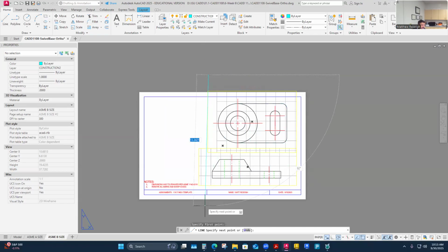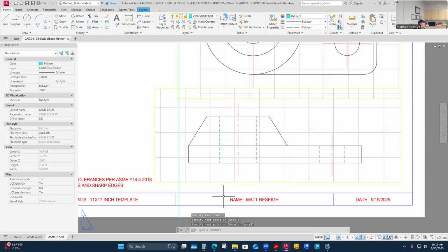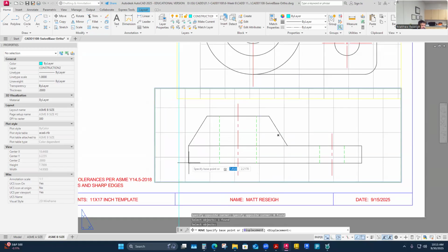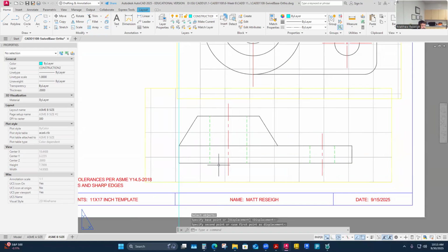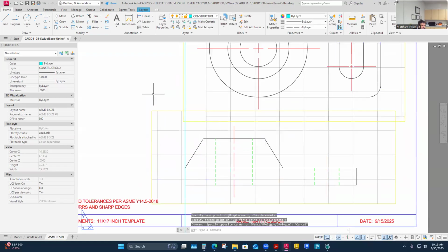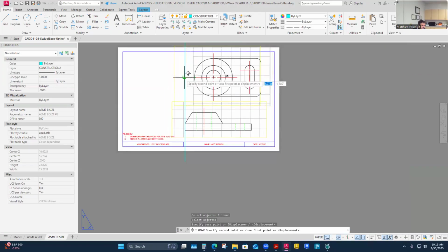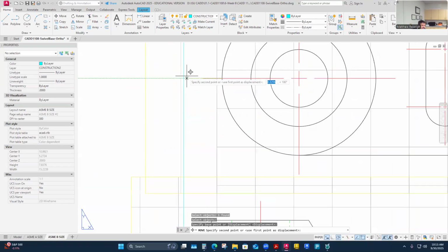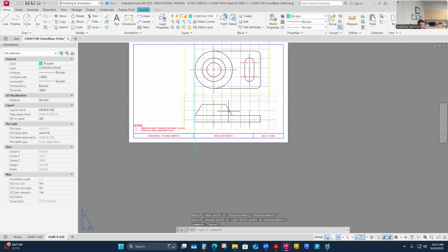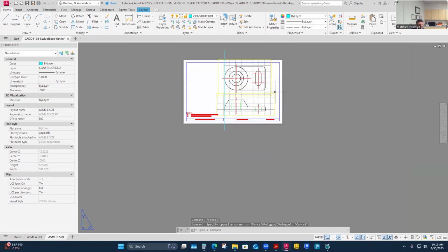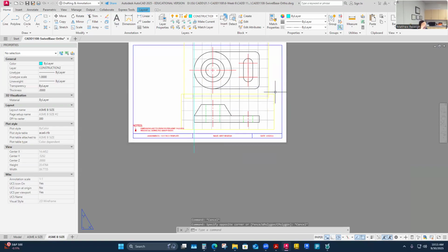Yeah, it looks like it's going to be somewhere in this region that's going to fit. I'll move this viewport by this object, maybe just right there. Sure. I'm going to move this one by the same, something that's orthographically aligned like that. I've got them orthographically aligned. Yeah, I'm going to hit dimensions and then I'll ultimately decide. I think once I get my dimensions, I'll probably determine 2 to 1 is just a little bit too big. But let's do the dimensioning first before I ultimately make that choice.